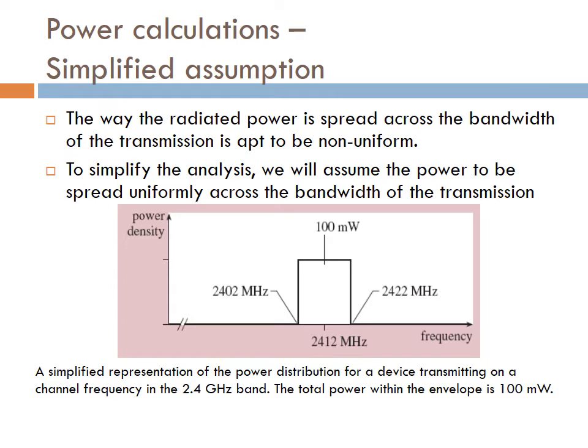The vertical axis in the figure is labeled power density. You have met this before, but I have not said much about what it is yet. Power density is a measure of the concentration of power in relation to frequency. For example, a power of 10 watt distributed across a continuous band of frequencies 100 Hz wide gives a greater power density than if distributed across a band 10 kHz wide.